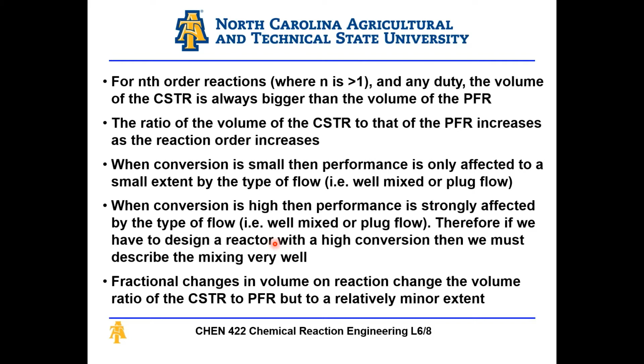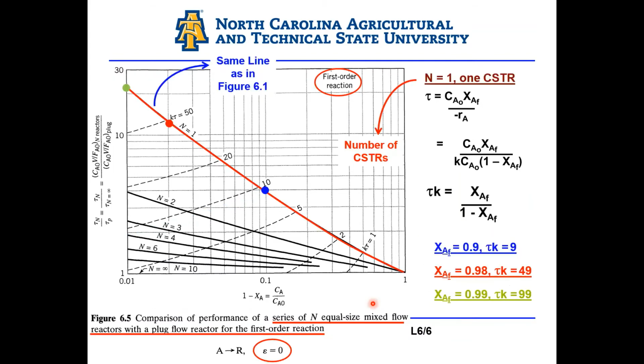Something to learn, something to always know. One of the important points to learn from this course: fractional changes in volume on reaction change the volume ratio of the CSTR to PFR, but to a relatively minor extent. And this refers to this chart up here,